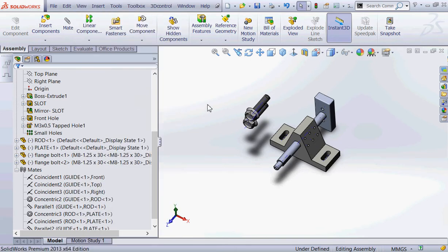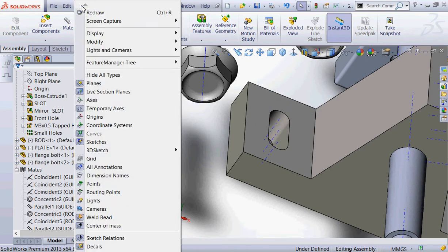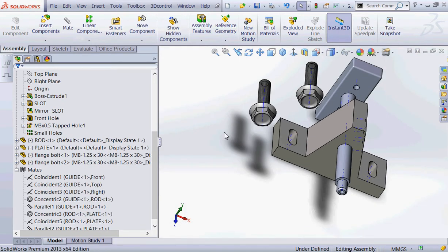So I'm going to hold down my left mouse button and I'm just going to drag this part into my assembly. You can only add fasteners to an assembly. You cannot add fasteners to a part. I know that might sound interesting, but some people actually will try to bring fasteners into a part file and it won't work. Alright, you can only bring part. Now you want to select the M8-1.25x30 configuration. That's at the very bottom. And you want to say OK.